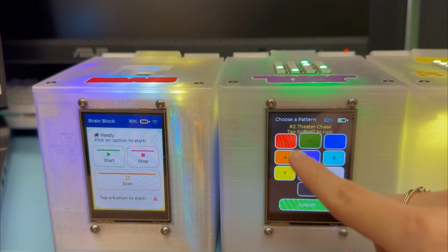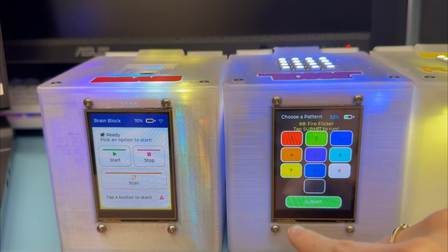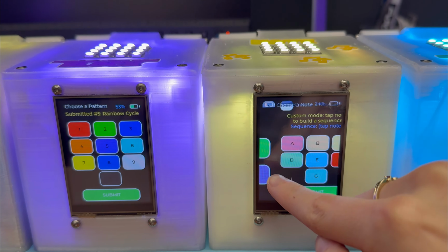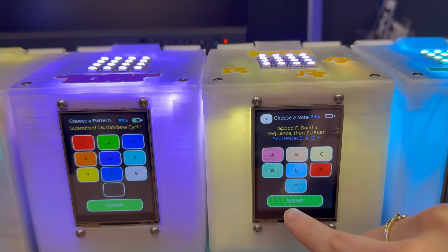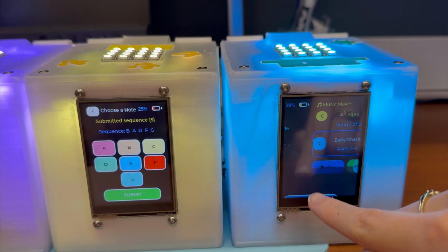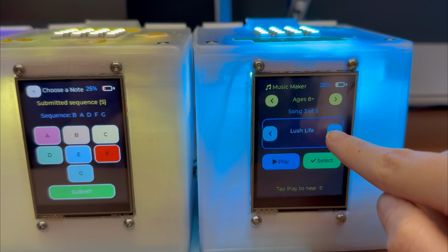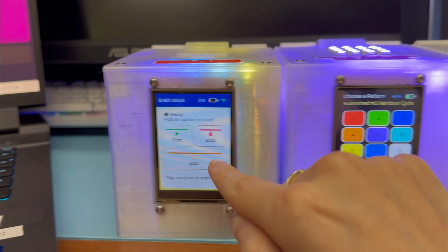Finally, the music sequence block allows you to choose from a list of pre-programmed melodies. We snap the brain block on and execute a quick sequence. This confirms that our block hardware is correctly receiving commands over I2C to manipulate the WS2812 LEDs and the LM386 audio amplifier.